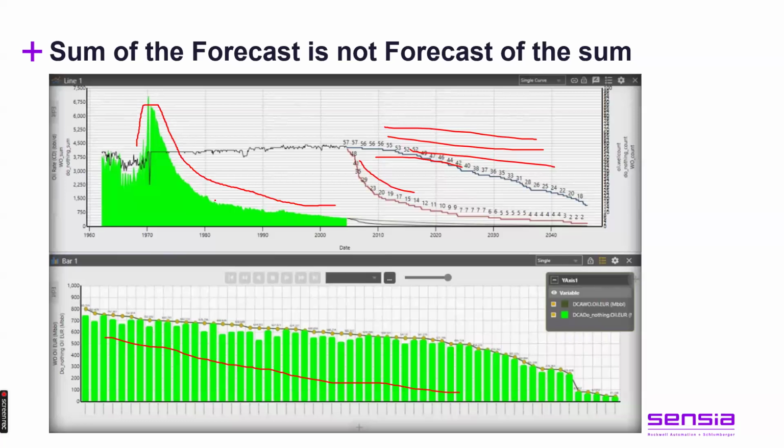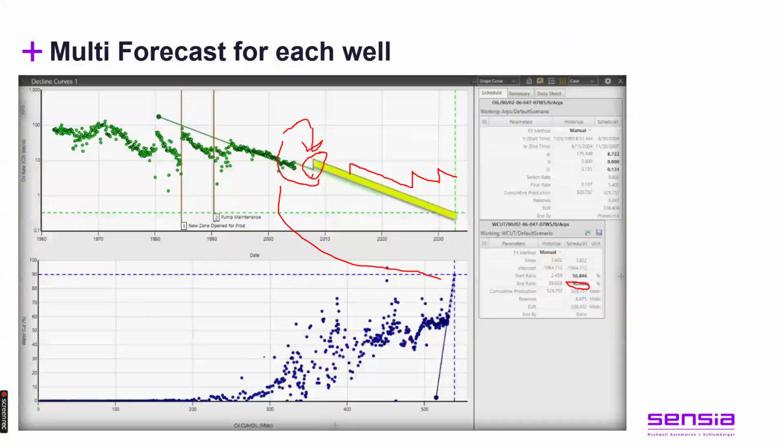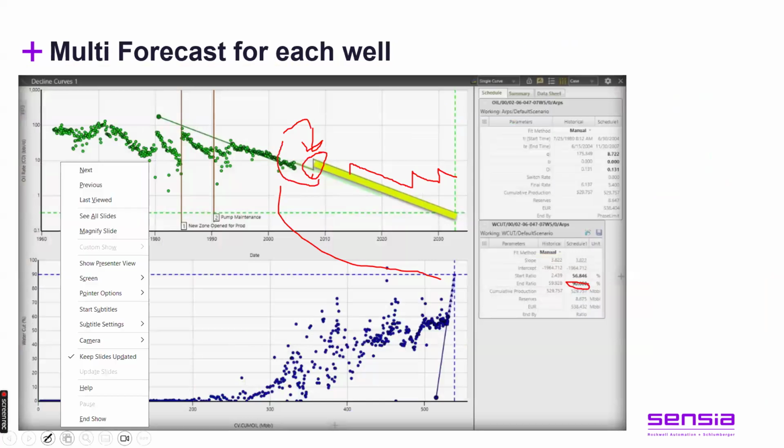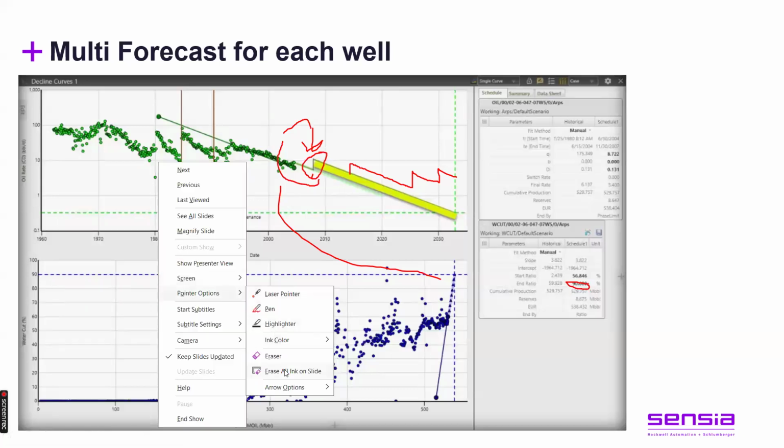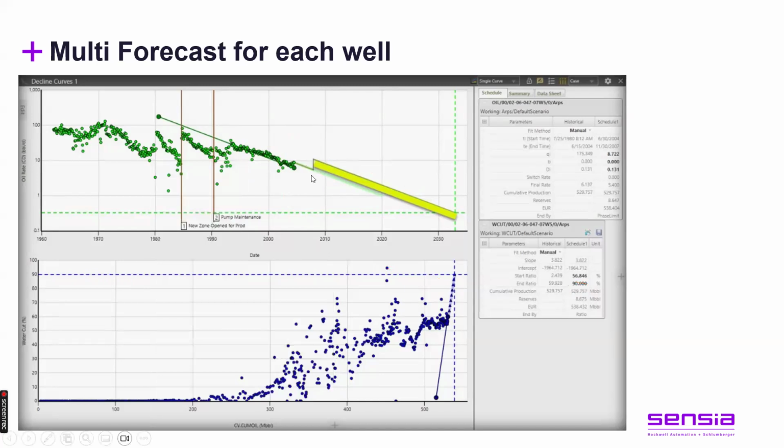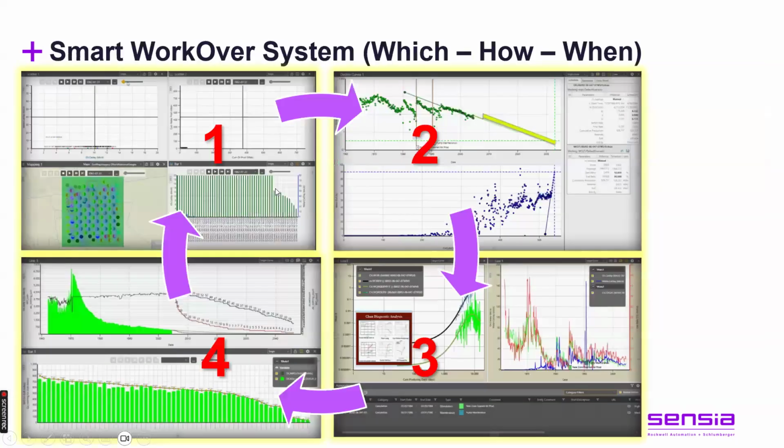Now, I have two scenarios, as I told you. The do nothing scenario. If you don't do the workover, what will happen? Remember this plot? If you don't do the workover, what will happen? You have to stop your well here. When you stop this well, this well will die, right? Unless you do something, because I reach 90% here. I cannot produce from this well. So I will lose the well if you do nothing. So often we run this do nothing scenario, which is this one.